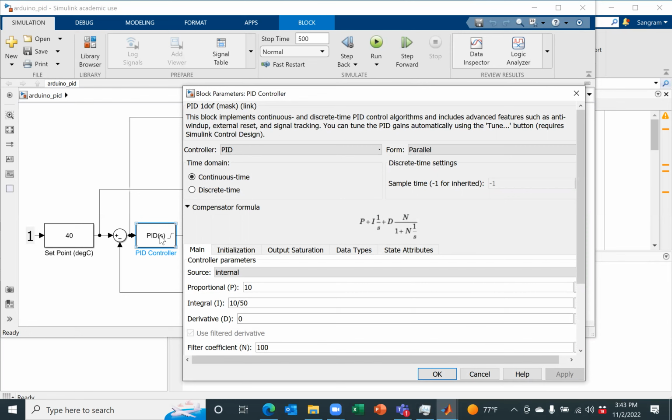What you do is you collect the data from the heater, get the relationship between the input and output, and find out whether the first order model, second order model, or zeroth order model gives you a good fit. So you do a system identification based on the data. Then use that system identified model to design the PID controls, and then use those PID gains for actual control.